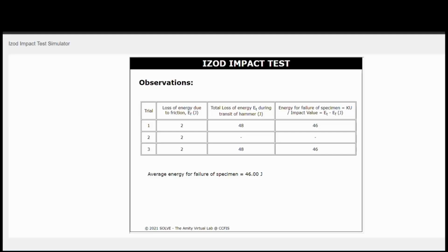In conclusion, the impact test is a test used in studying the toughness of a material. Toughness is connected with both the ductility and the strength of the material, and the impact test involves the sudden and dynamic application of the load.